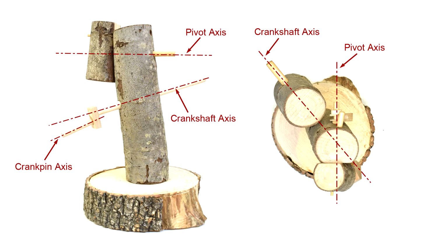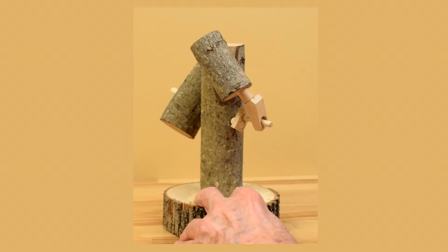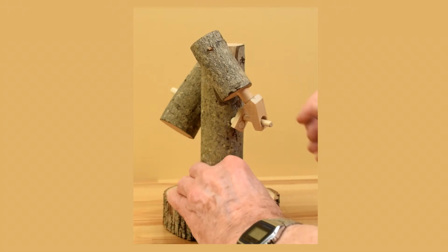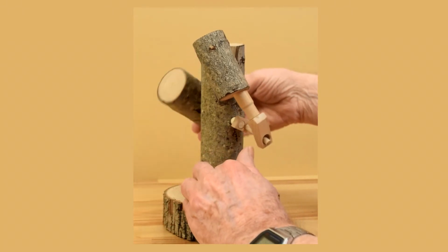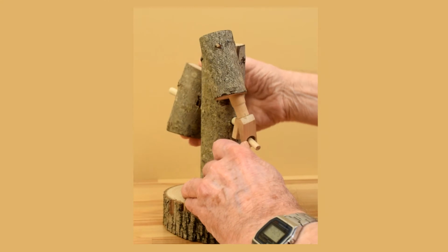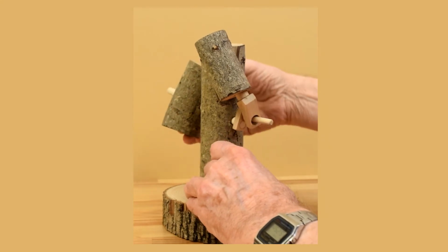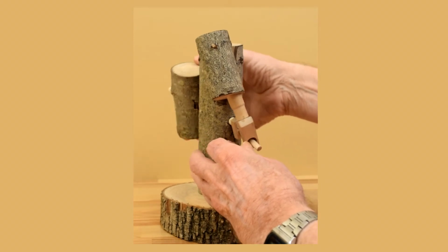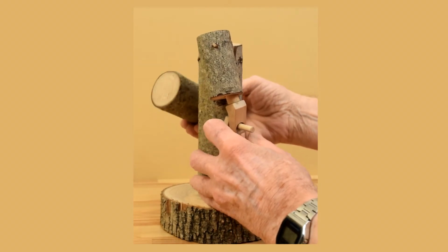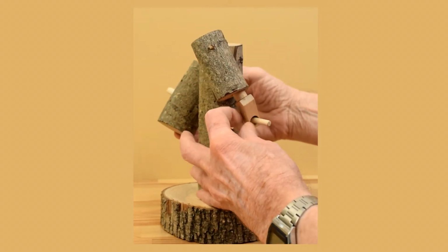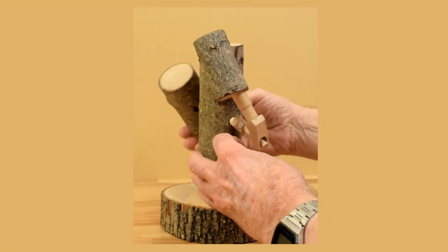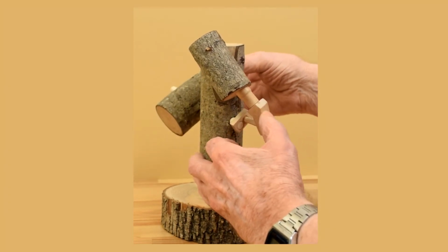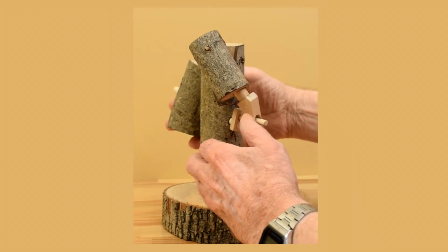The joint axes seem almost absurdly skewed, and I worried that I'd already gone too far. Mk2 didn't fare well on the freedom of motion checks. It wouldn't rotate freely in either direction. The rod end joint kept binding. Just playing with the rod end joint, rotating the rod end a bit, and applying axial force at some points in the motion allowed full rotation in both directions, but nothing close to free rotation of the original branch engine,